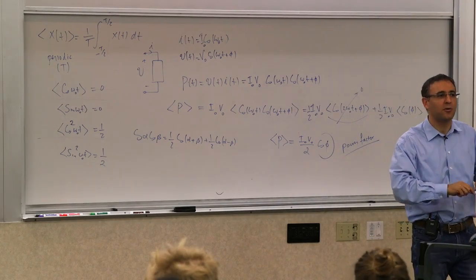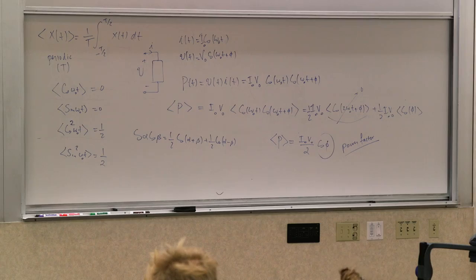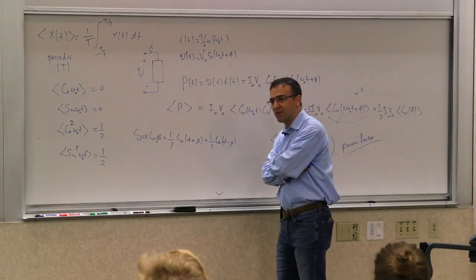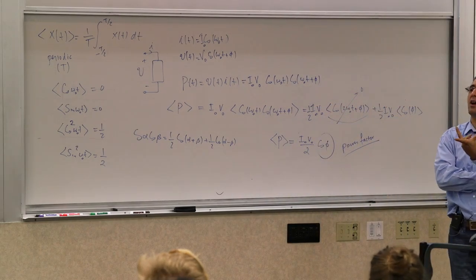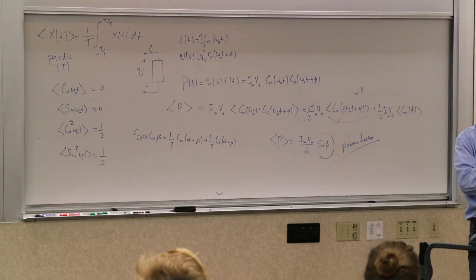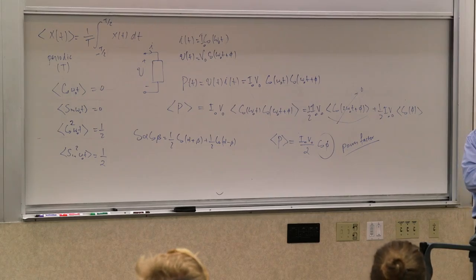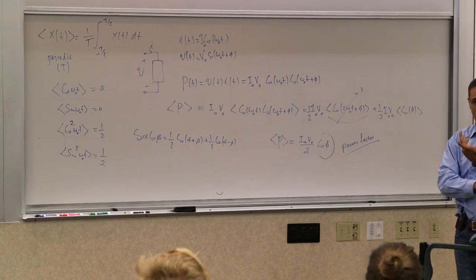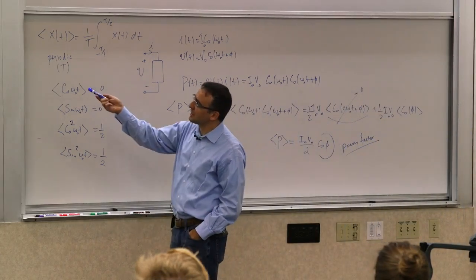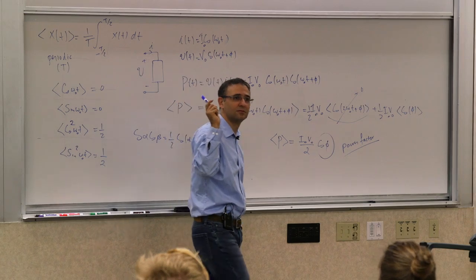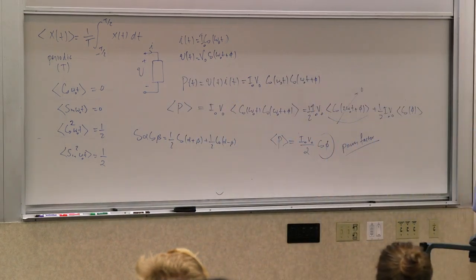Now, what is power factor? Why does power factor matter? Because you can have a large current and large voltage, but deliver no power. Let me give you an example. If you have an inductor, a pure inductor, if you drive it with a certain voltage or a certain current, right, what happens? You get a current and you get a voltage, but they're 90 degrees out of phase. How do we know it's 90 degrees out of phase? Because its impedance was j omega L. There was a j, right? So how much net power do you deliver? 0.